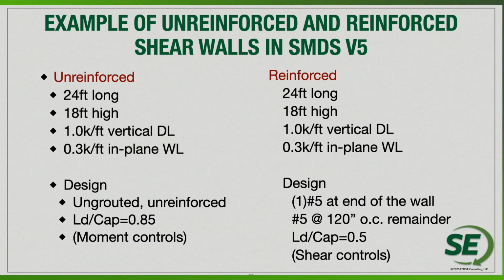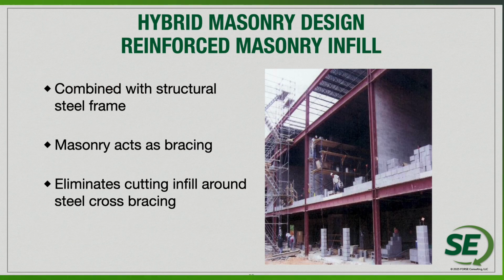So certainly if we look at the two designs, I think definitely the one on the right, slight cost increase with the number 5 bars that you would have to have in the design and a little bit more grout, is going to give us much more capacity for that design.